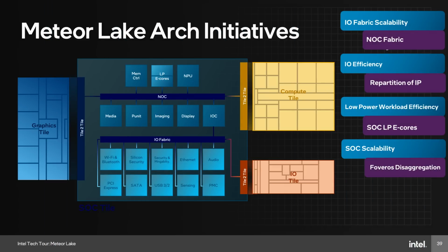In the Tiger Lake architecture, think about it like we have one highway. That highway was getting shared with the IPU and the VPU and the display. So if there is a jam, then some other IPs or agent IPs actually had to wait. In our case, the way I would say this is that Meteor Lake is the true SoC that has multiple highways for different agents. Meaning that, for example, if the IPU wants to talk to the memory, you don't necessarily have to wait for the others. You have your own channel to go to the memory. If you have display, which needs a higher prioritization, it will go to its memory link directly.